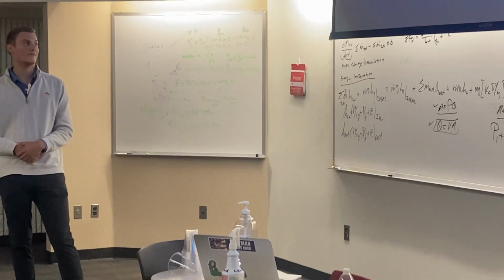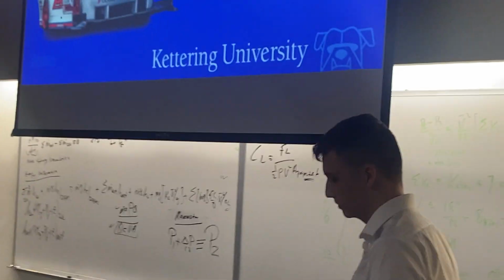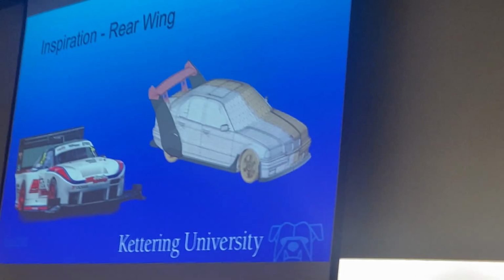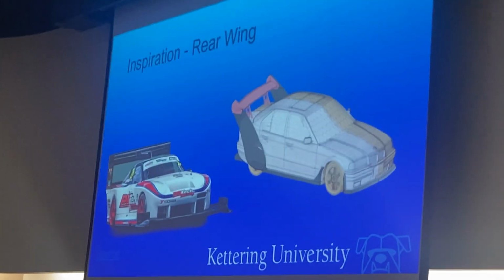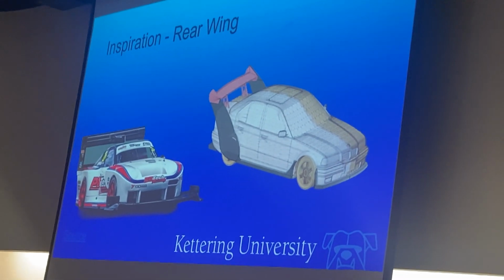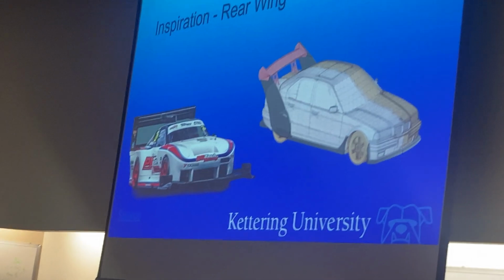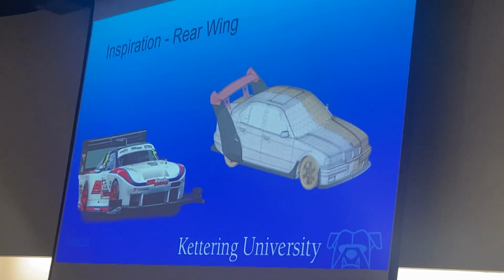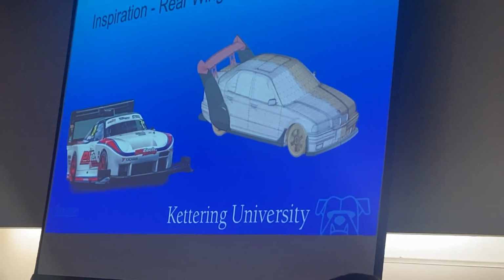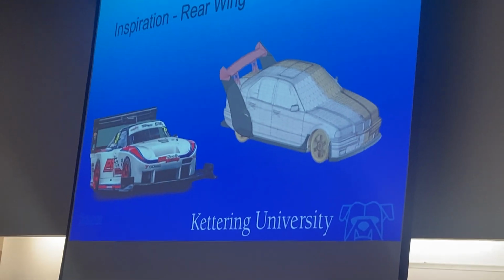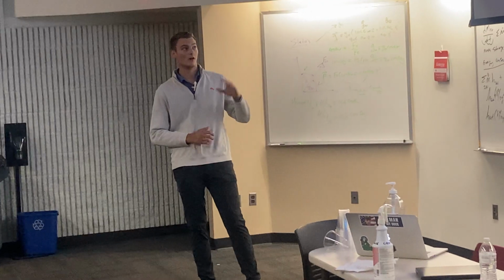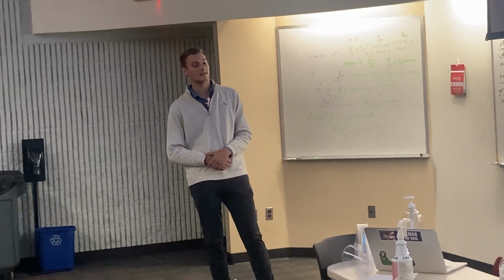So next was definitely the most eye-catching thing of the car, which is the rear wing, and it is built in to cover up the rear wheels, so it kind of gets into the fender strake things like we were talking about on the Porsche. And I cribbed this from a hill climb racing car, and these cars always have ridiculous wings because usually when they're climbing up mountains like Pikes Peak, the air gets thinner as you go higher up, so you need more things to generate downforce since your density decreases. So that's why they're always very large, massive wings.